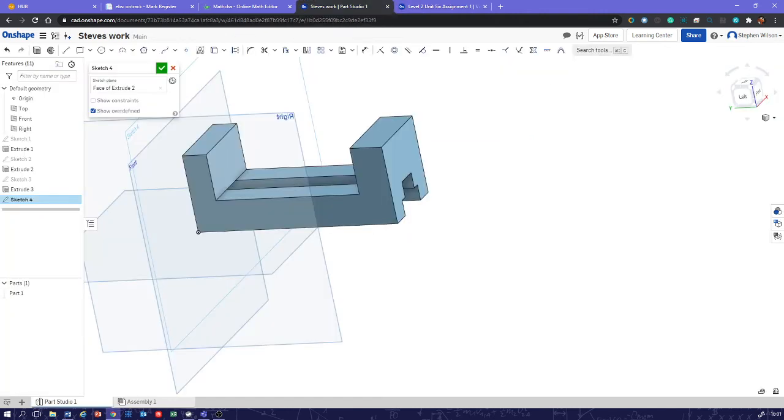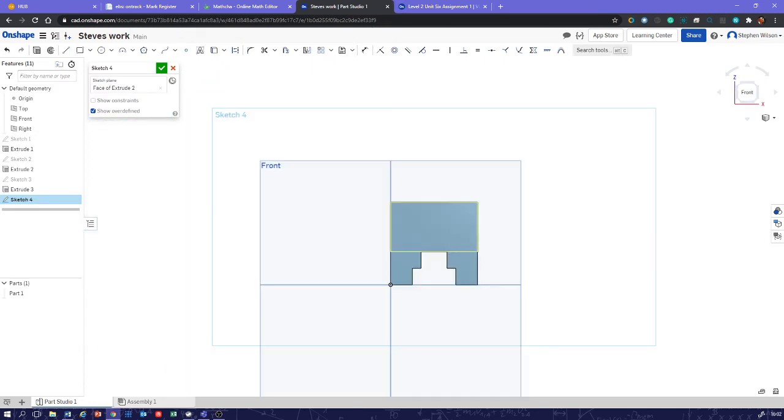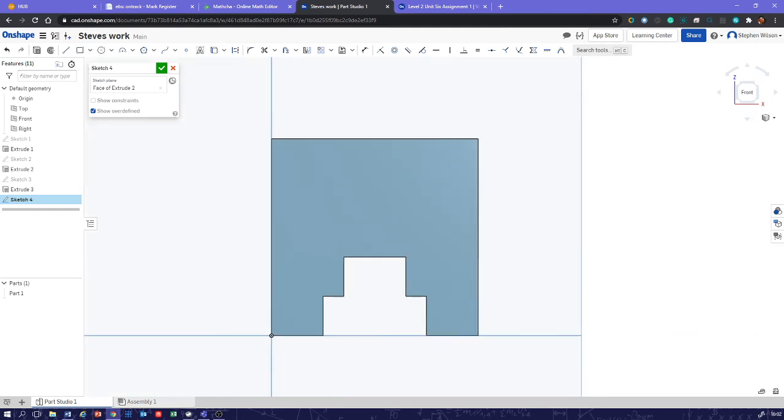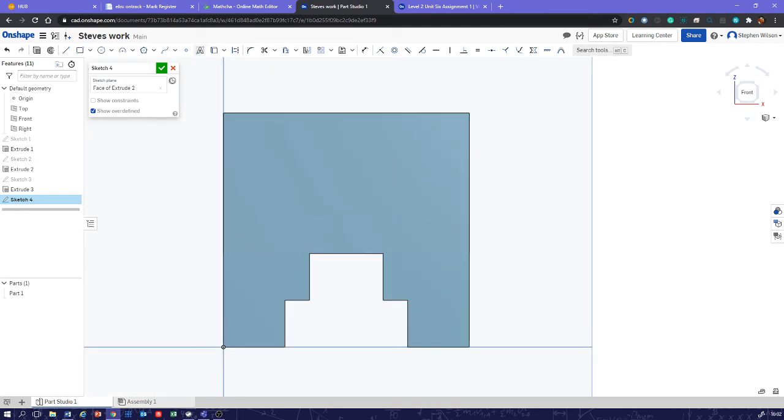Okay. So we're just going to make that point first. Okay, so we've said that. N, normal to sketch plane. So we're flat on. I'm going to choose a point, and I'm going to just bring that point out. Can you see there? I'm just selecting the midpoint of that line, and that dotted line tells me that that will stay in line there. So I've selected my point.